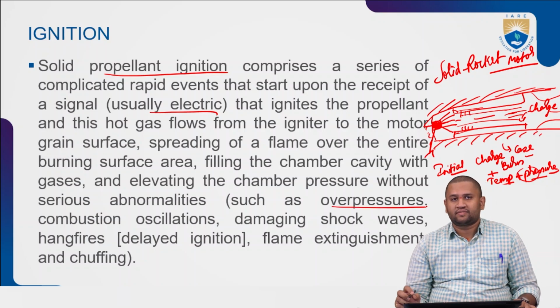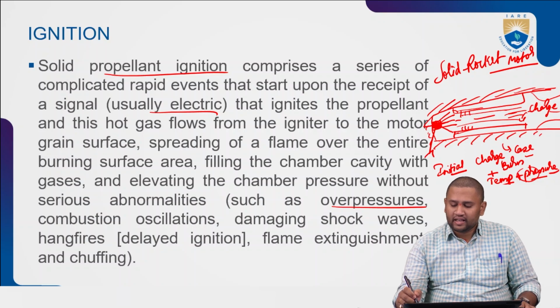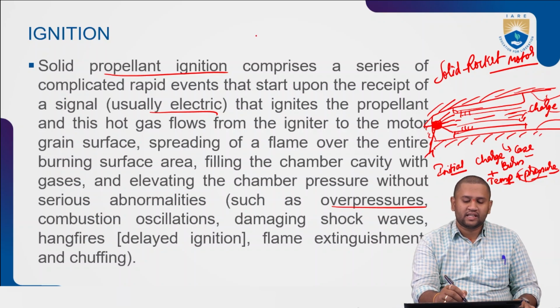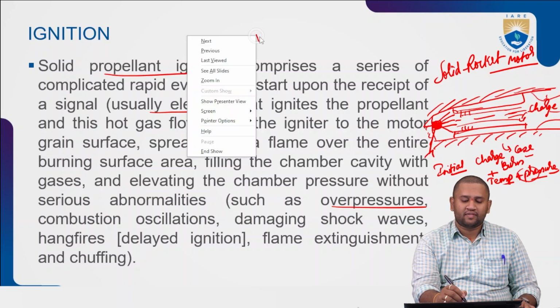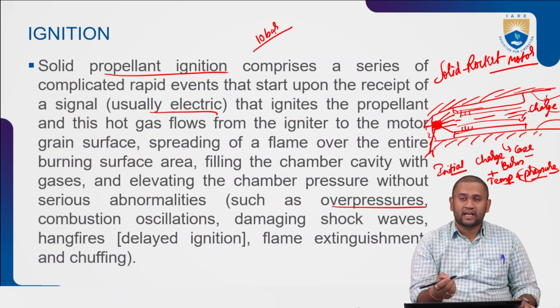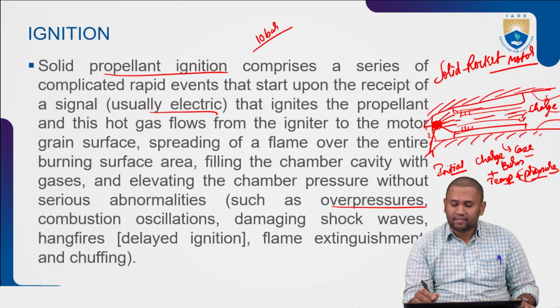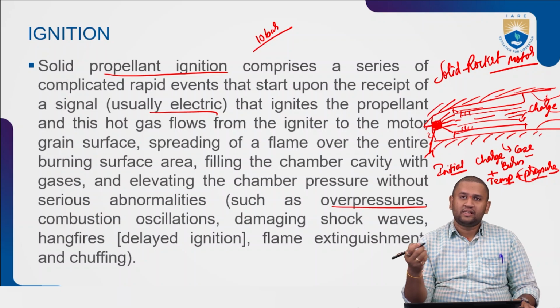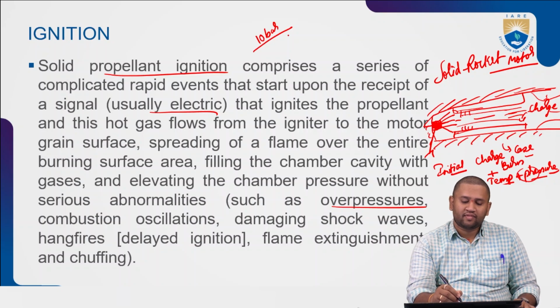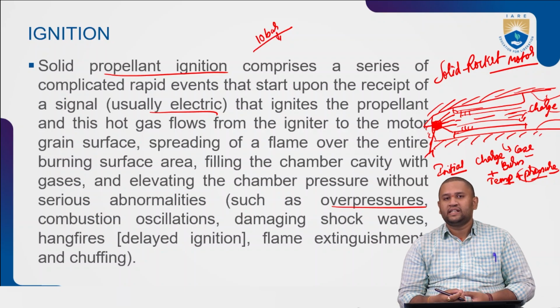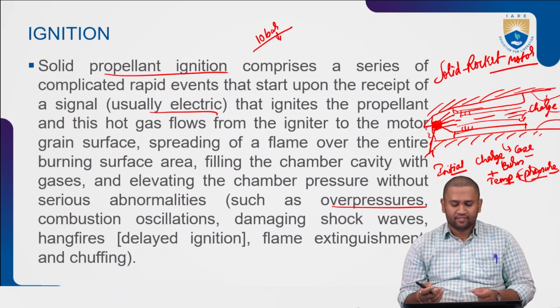the overpressures, right? What do you mean by overpressures? Basically, the nozzle has been designed to withstand certain pressure, let's say some 10 bar, but the pressure generated by my initial charge, particularly the pyrotechnic charge, as well as the grain will exceed this 10 bar, creating a small pressure abnormality at the nozzle, right?